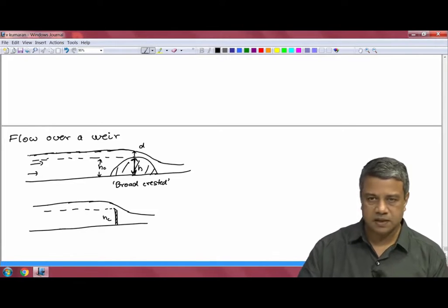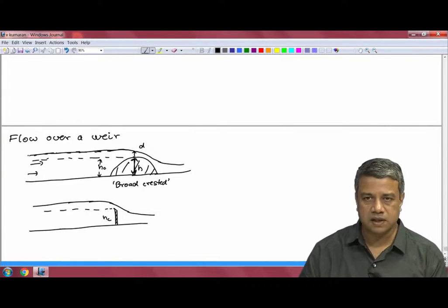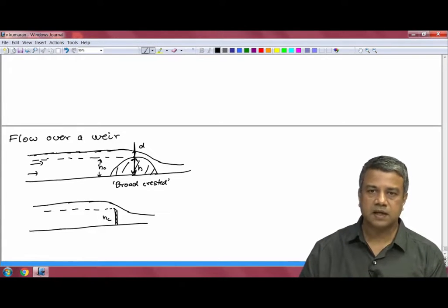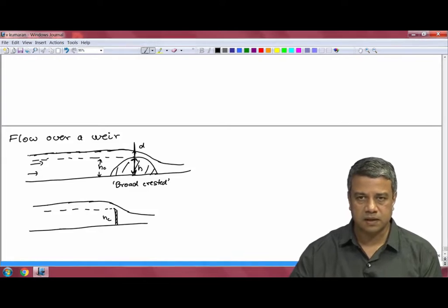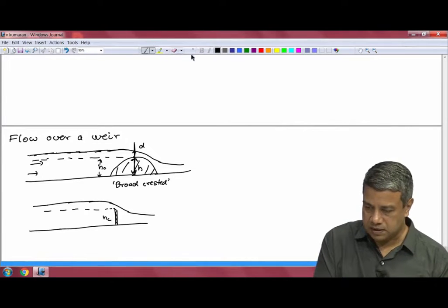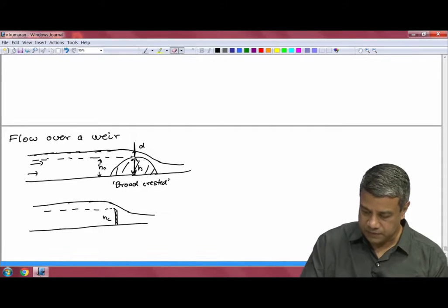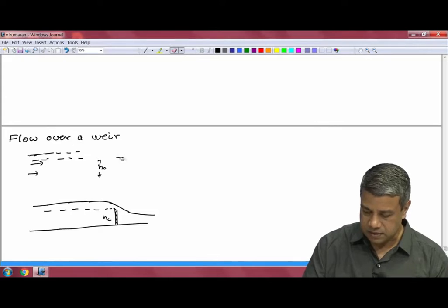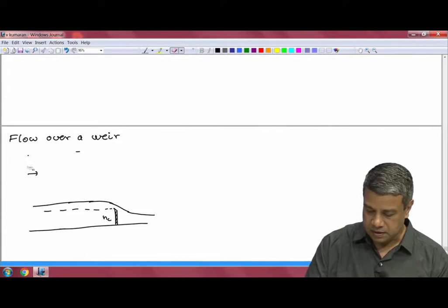Okay. So, at this maximum location, if I find out what is the height of the water above this just by inserting a rod, say, and finding out how much gets wet, from that I can calculate what is going to be the flow rate and the velocity past this. Okay. So, I will show you how to do that. First thing I will do is to draw a more accurate figure for this broad crested weir itself.